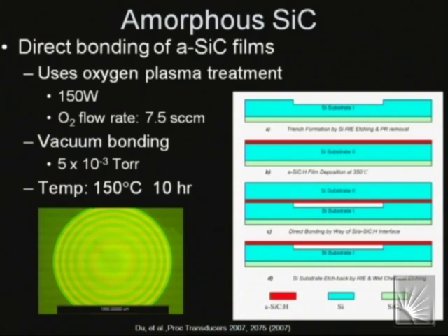We did find, however, since we could modulate the stress quite nicely, and we knew that hydrogen effusion was likely the mechanism, we thought, well, let's look and see how we could use this film in a host of micromachining applications. And one we were particularly interested in is bonding, because in many bio applications, especially those directed towards microfluidics, bonding of two separate micromachined substrates is often critical in realizing the final device.